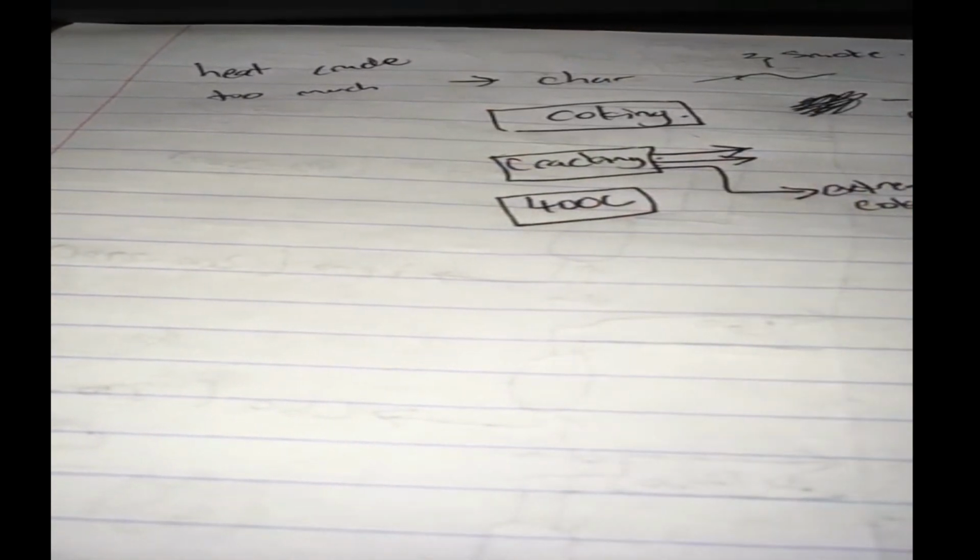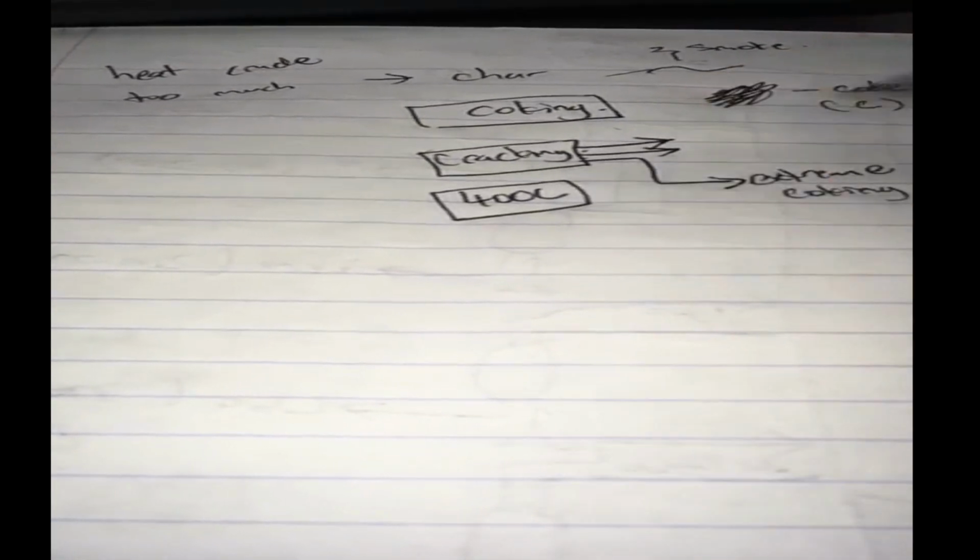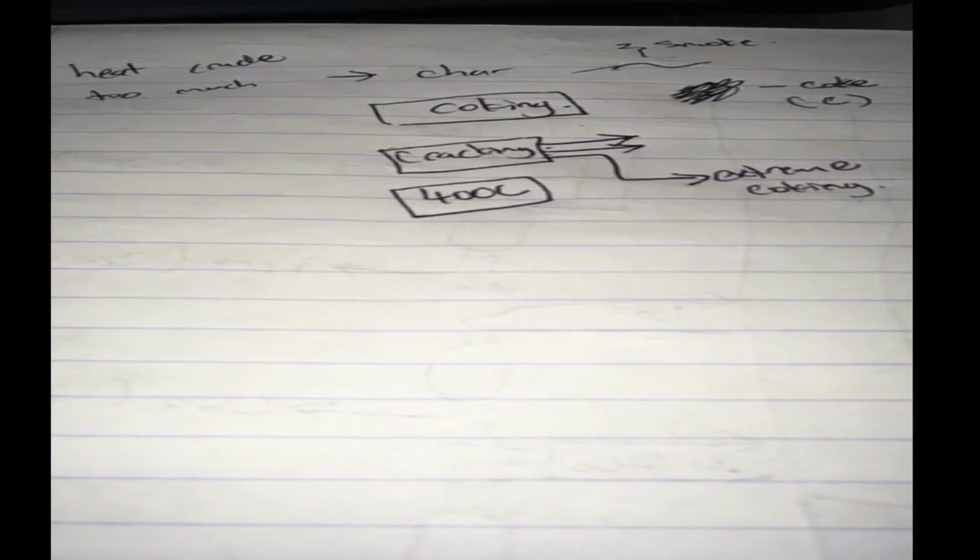Alright? So, we don't want this cracking or all this to happen in our distillation tower. The safety barrier, a very easy to remember rule of thumb, is that at 400 degrees, cracking will start happening. And if cracking starts to happen, then your crude tower is kind of messed up. So what do we do?